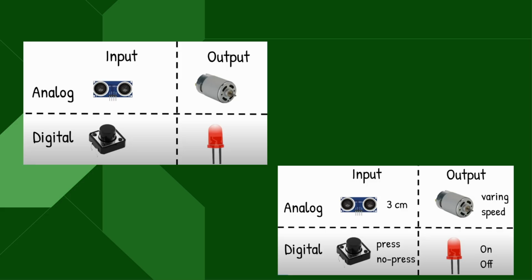Ultrasonic sensors have a minimum range and a maximum range. If you are below the minimum range, it will start to freak out and say that your object is something like 1,023 centimeters away, which is clearly not correct.